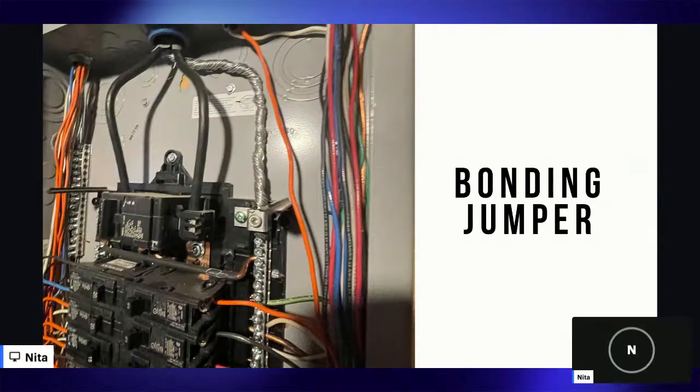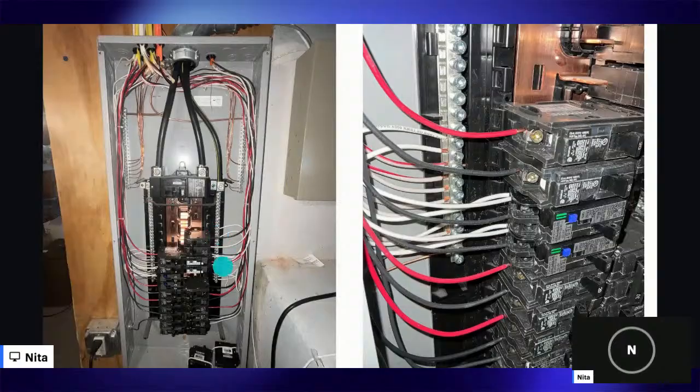If we are talking about a grounding wire that's green or bare, where should it be? Your grounding bus bar. That's correct. These are our branch circuits. So if you're looking for a green or a bare wire, you would only be looking for it on your grounding bus bar. Okay, so those black things have nothing to do with your lesson today? The circuit breakers? No, I haven't gotten into circuit breakers yet. I just mentioned them to say that they are connected to the bus bar.